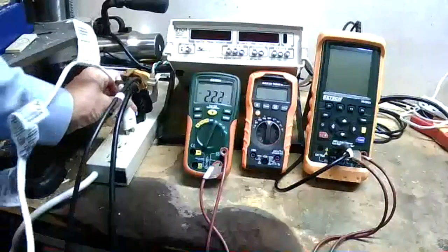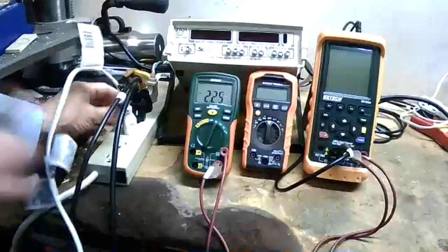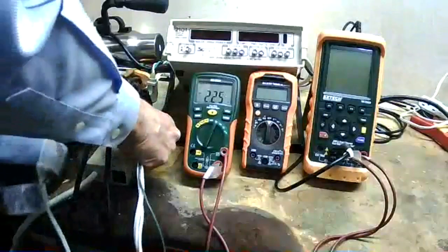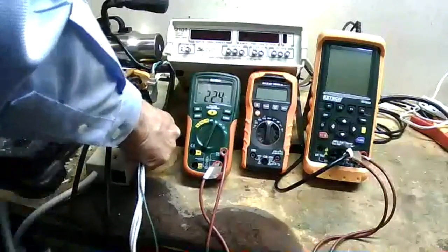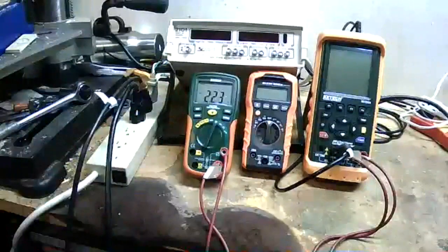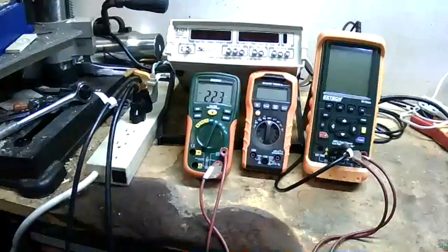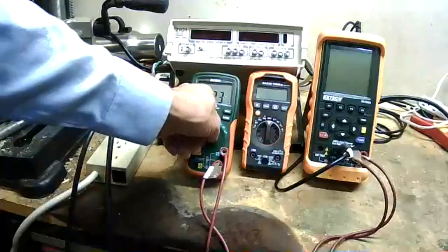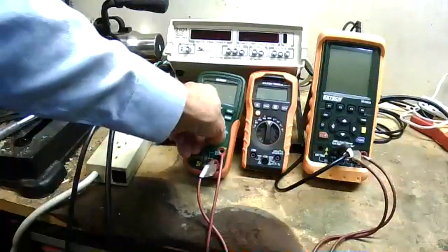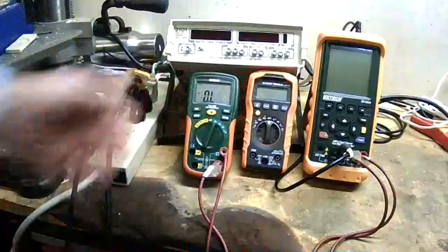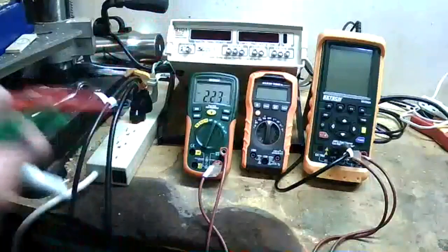So I plug the extension cord into the outlet strip, and I'm going to pull it right back out because I should actually make the connections before I plug it in. I like to have as many open switches, open circuits between me and 120 volts as possible. The meter's telling me it's been on too long. It's going to turn off if I don't do something, so I turned it off and back on.